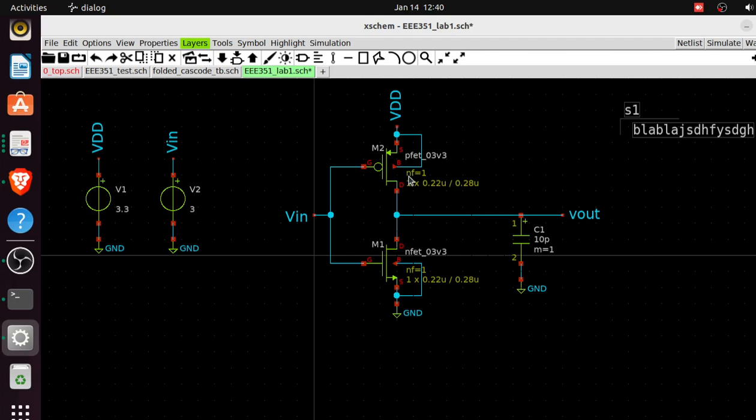When it comes to CMOS design, basically as a designer, all you're doing is trying to size the transistors. By sizing the transistor, anything you desire the transistor to do, it will get done, as far as you have the mathematical workings for it. So if you want the MOSFET to conduct this value of current, then all you need to do is go to the current equation and specify the sizing that you want. Then you have the current that you want.